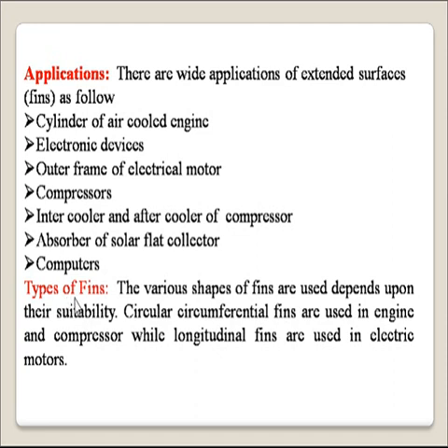Now we'll discuss types of fins. The various shapes of fins are used depending upon their suitability. Circular circumferential fins are used in an engine to cool the engine cylinder, and also used on the compressor cylinder, while longitudinal fins are used in an electric motor to dissipate heat from the electric motor outer casing.